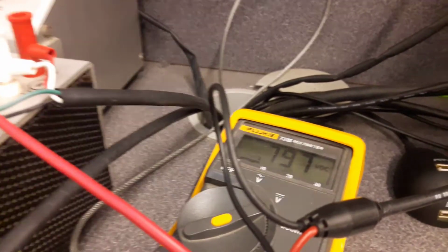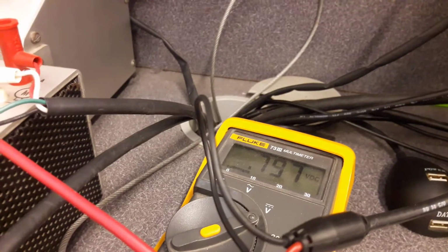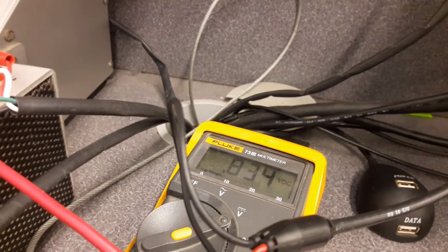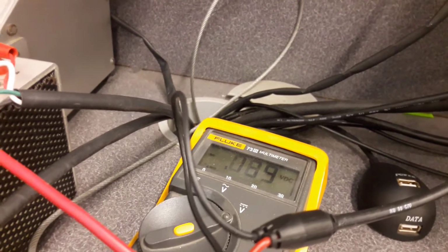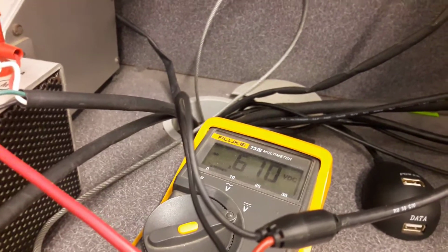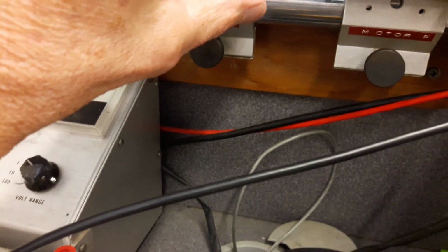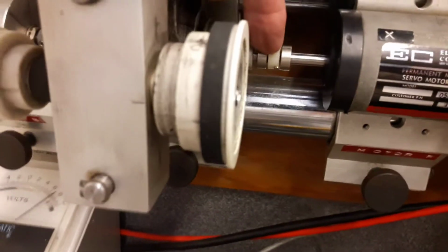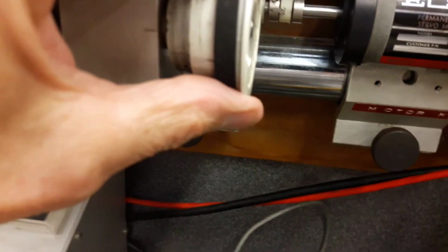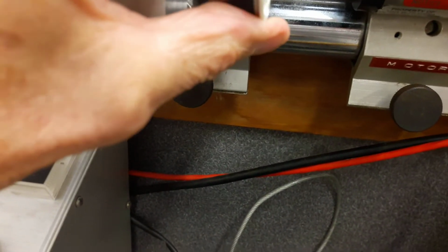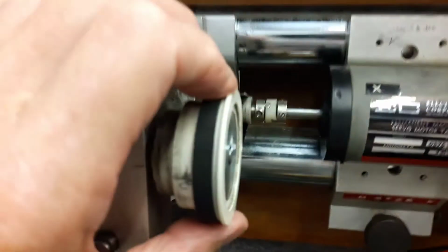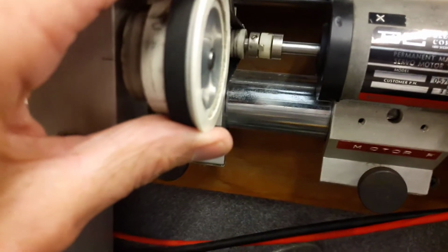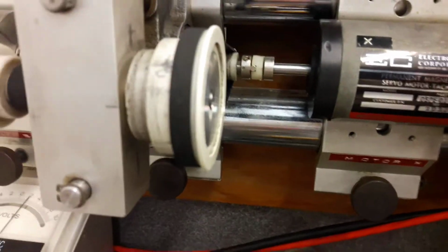So before you do another run, what you need to do is calculate that value, and then you first change this until it's in the center of that range. I don't remember the values, but I can kind of do it by hand too if I want to. If I look at where it is, I notice that here I have a pin for this coupling in that position, and then I turn it down. Oh wow, it's gone way around, almost 180 degrees. So if I set that pin halfway in between,